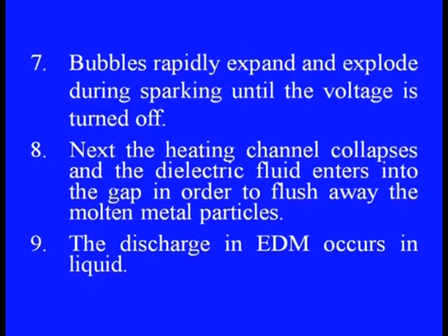A small amount of material is evaporated on the electrode and workpiece at the spark contact point. The bubbles so created rapidly expand and explode during sparking until the voltage is turned off.